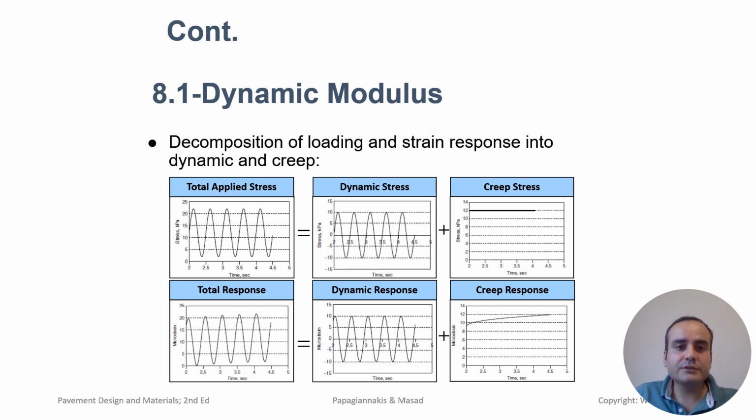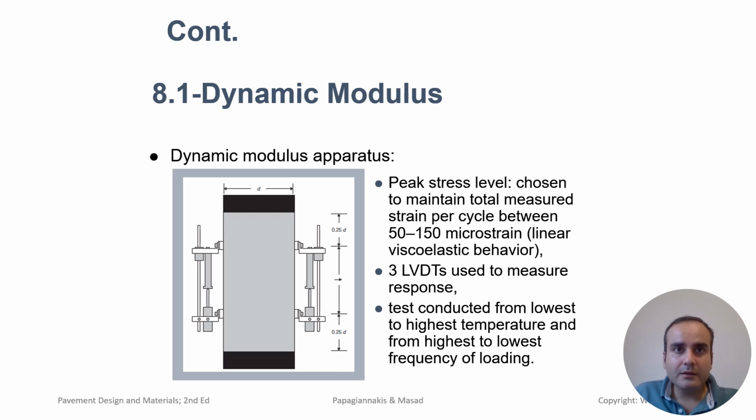This slide shows the decomposition of loading and strain response into dynamic and creep. This slide shows the dynamic modulus apparatus. The test is conducted from lowest to highest temperature and from highest to lowest frequency of loading.